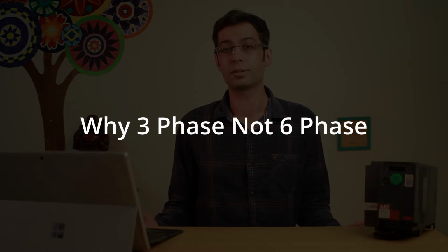Due to the cost, we are using 3-phase. As you know, 3-phase can self-start a motor. There is no requirement of 6-phase. If we use 6-phase power supply, it will double the number of protective equipments used in distribution, in transmission. For example, you will have to use 3 times the number of circuit breakers, 3 times the number of transformers. They are in use but not as much as 3-phase power supply.